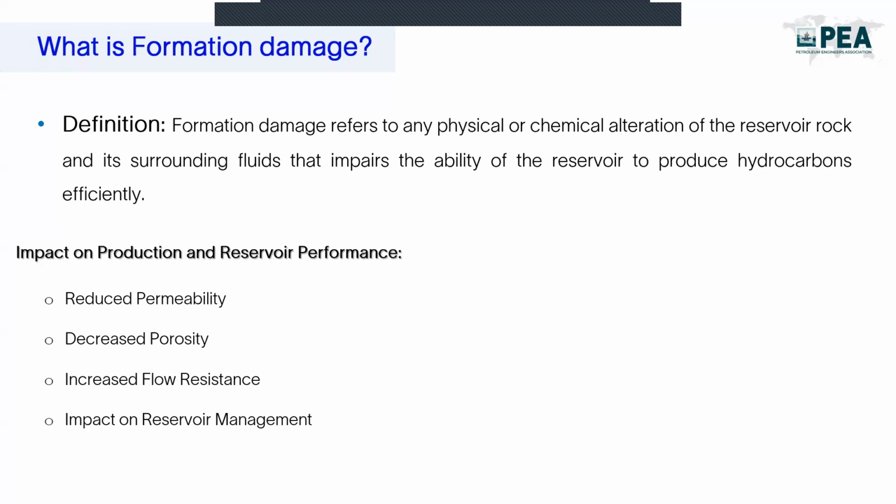The last impact, and I see it's a very serious one, is the impact on reservoir management. Formation damage impacts reservoir management strategies by limiting the effectiveness of any enhanced oil recovery techniques that you may apply. For example, techniques like water flooding or gas injection may be less effective if the formation damage prevents proper fluid injection or displacement.